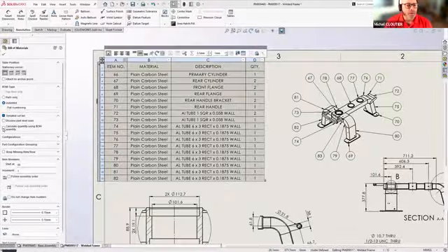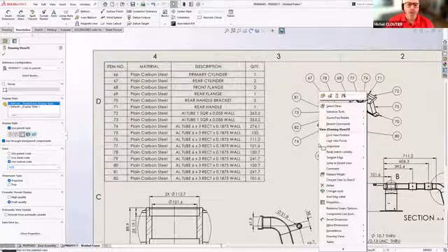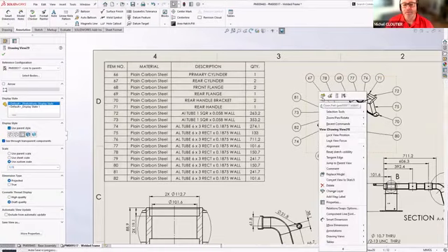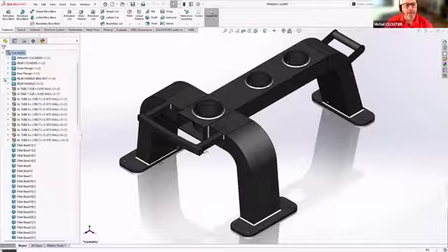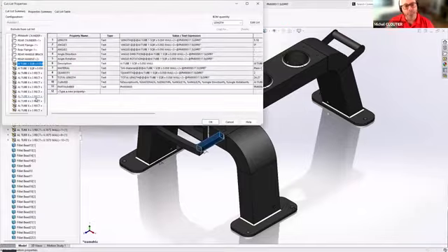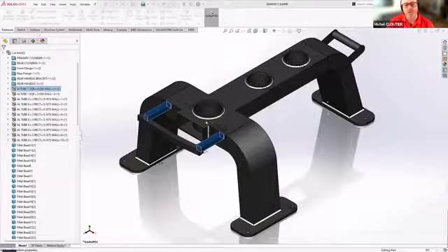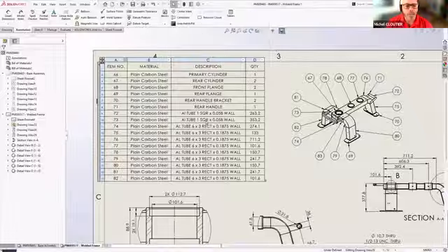So when we use the calculate quantity using BOM quantity, it's actually going to look at the settings we've used in my cut list settings and use that as the BOM quantities rather than the piece count, right? So if in my BOM quantity cut list properties, I use length, that's what it is going to use in my detailed cut list bill of material.